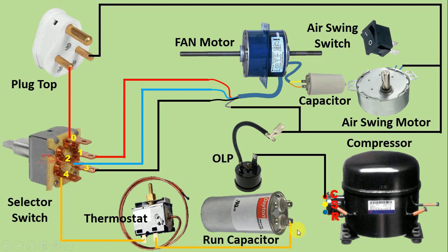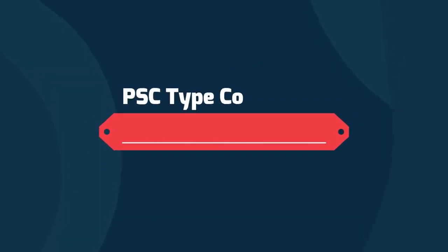Now to the terminal at which we provided input power supply, from there only loop a wire, and in this compressor with running terminal, that is with R terminal, connect this wire. This means from this terminal connect a wire directly to R terminal. After this, in this capacitor here, from second terminal of this capacitor connect one wire, and with starting terminal connect this wire.